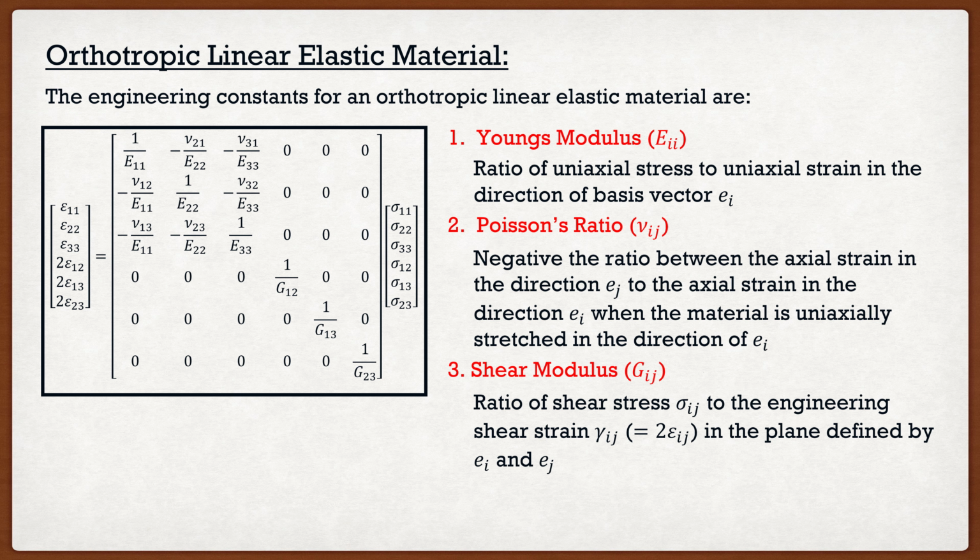We had that C, which is a stiffness matrix. Now if we look, we actually have strain on the left-hand side, and we're taking a matrix and multiplying it by stress. I already hinted that once we do this inverse, the matrix actually has a different name. So in this case, when we take a matrix, multiply it by stress to get strain, this is called the compliance matrix. And instead of C, we have it labeled as D.